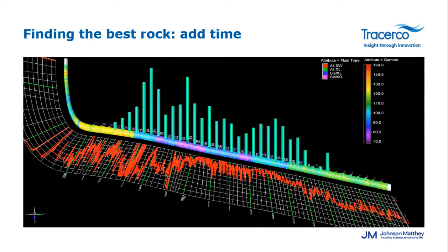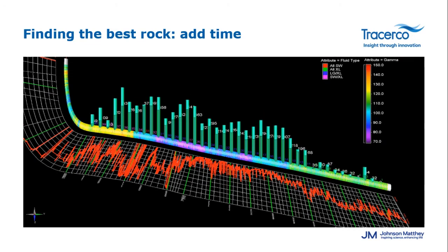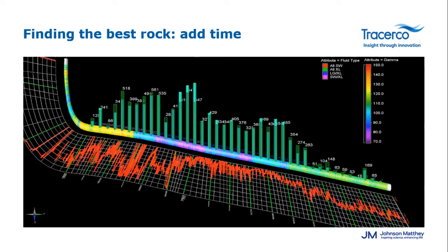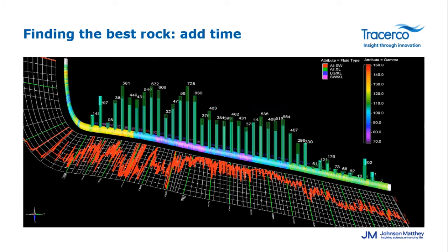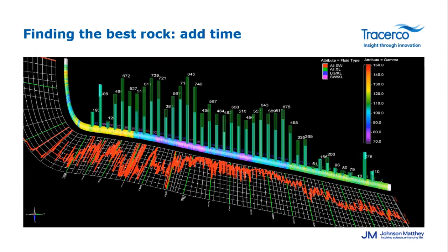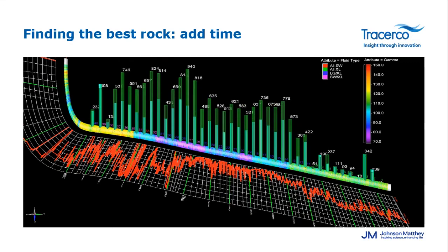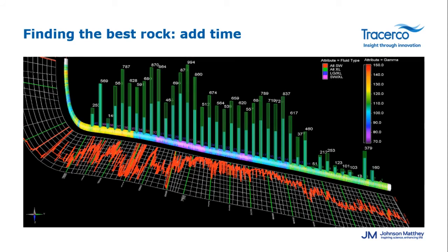I hope the animation will work for everybody and you will not experience too much lag. The solid bars present the change in production over time, and the translucent grid provides cumulative production over the entire project. Using this, we can see how a stage performed in 2 ways, the cumulative as well as over time. This also removes some bias in the cumulative data due to the stage's location, differences in cleanup over time, and other items that may affect early production. This is particularly handy when evaluating choke changes and artificial lift changes.